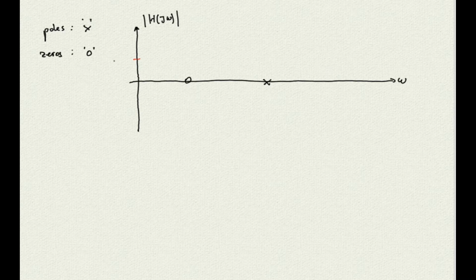We start our diagram at the value for omega equals 0, which is right at the intersection with the vertical axis. The vertical coordinate in that point is represented by the logarithm of a, remember how the generic transfer function is defined, multiplied by 20, since we are talking about voltages. Why this number? This number represents the value of the transfer function for omega equals 0, expressed in decibels, which we represent with the symbol dB. For now, just keep in mind that the dB is a measure of the magnitude in logarithmic format. We'll get back to that in a moment.